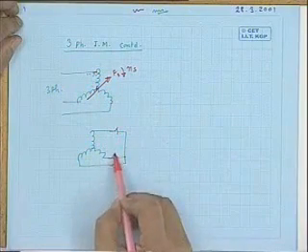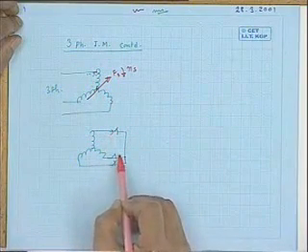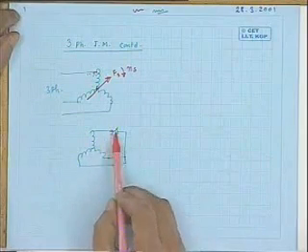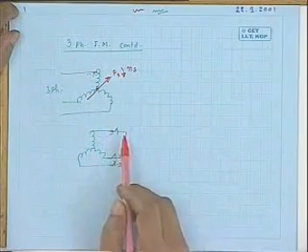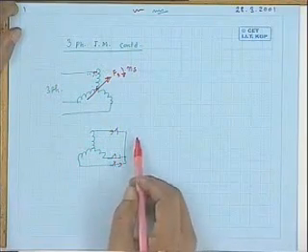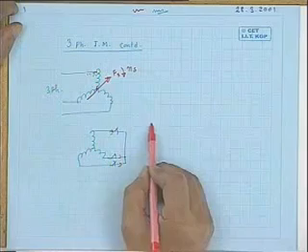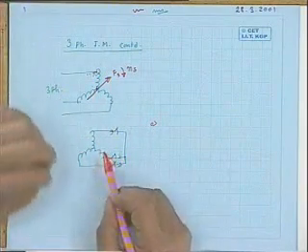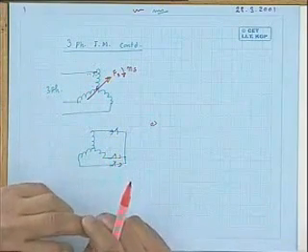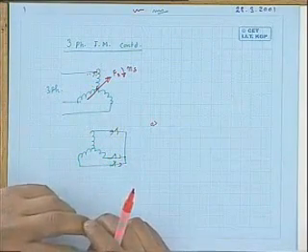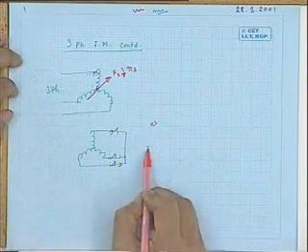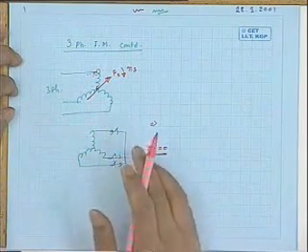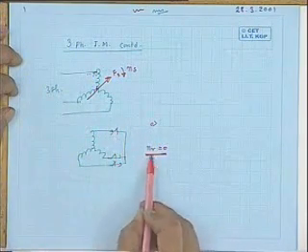However, the moment you close the rotor, there will also be balanced three-phase current flowing in the rotor circuit. And this current will also produce a rotating magnetic field. And I showed last time that with respect to a stationary observer, the speed of this rotating field produced by the rotor is how much? With respect to a stationary observer? Ns. At least let us consider nr equal to 0, suppose. Rotor speed is 0. I have just switched on the supply.